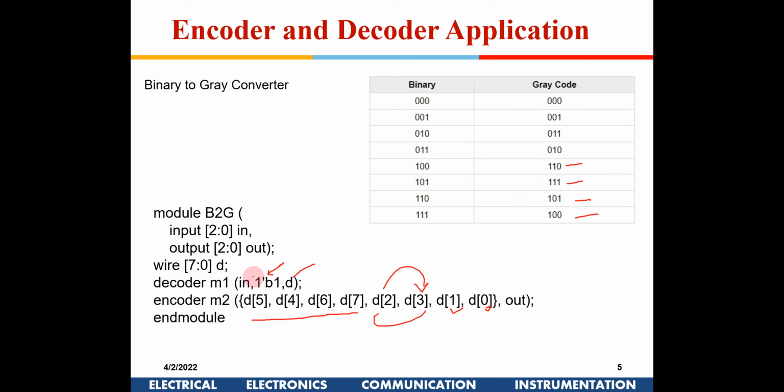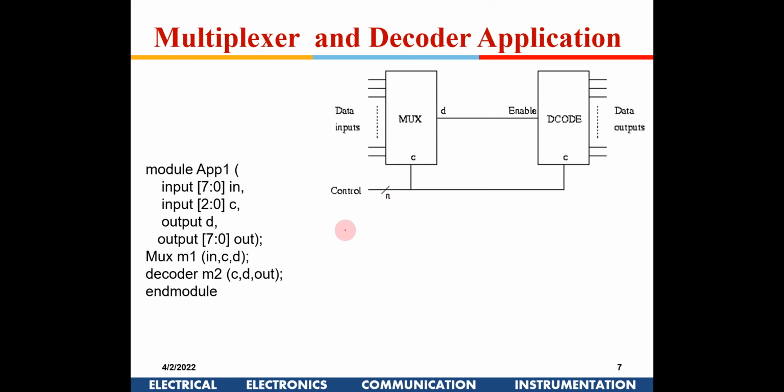One application of mux we are going to do today is, suppose I have a set of data available here, right, and that needs to be transmitted from, say, one chip to another. So I don't have to take the entire full lines here. I can just send a single line out here, right, and the control signals out here.